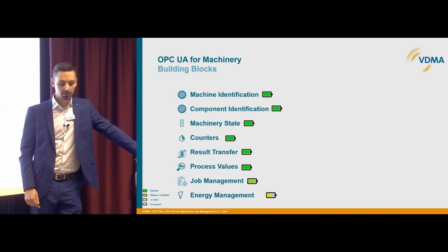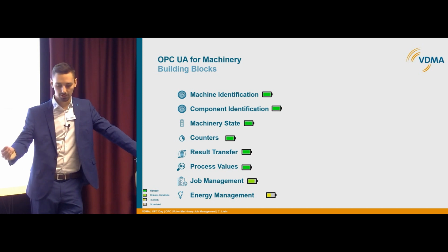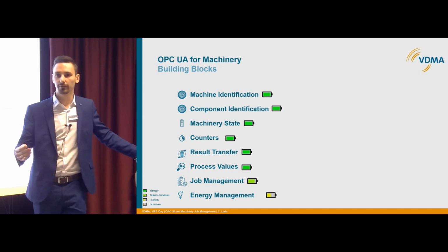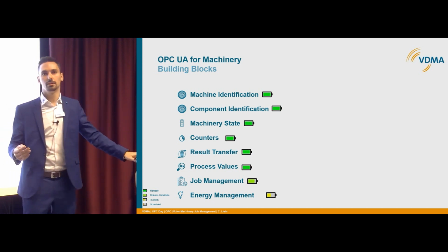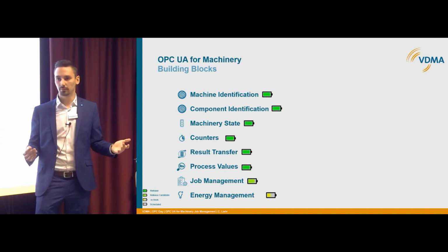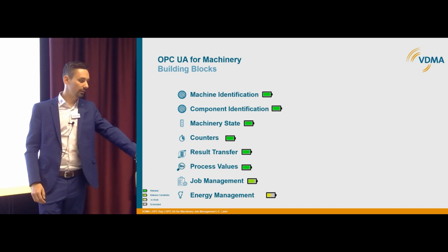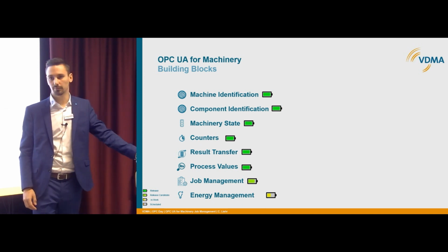To give you an example, if you want to monitor the temperature value of a machine tool, you get the metadata in the same way as, for example, a flow rate in a shot blasting machine, if you use the process values. The process value type in this case is an extension of the analog signal type of the PA-DIM specification from the process industry.